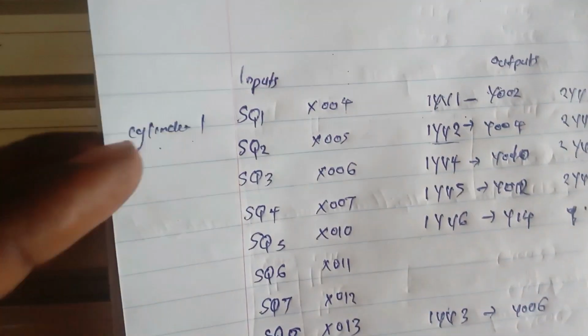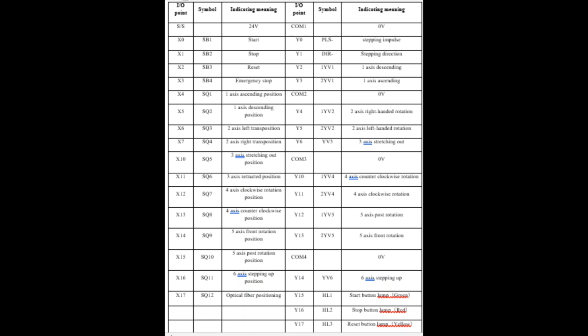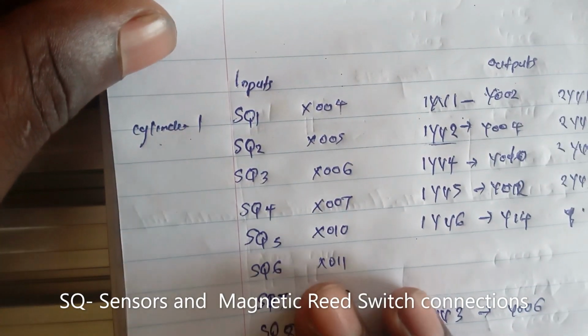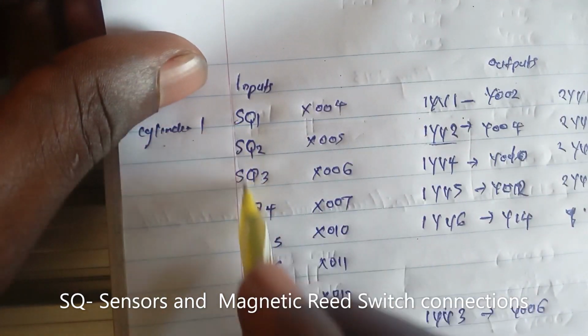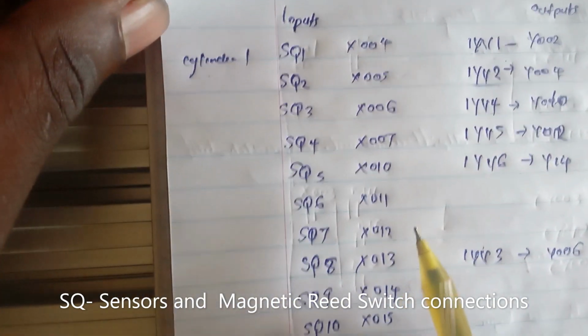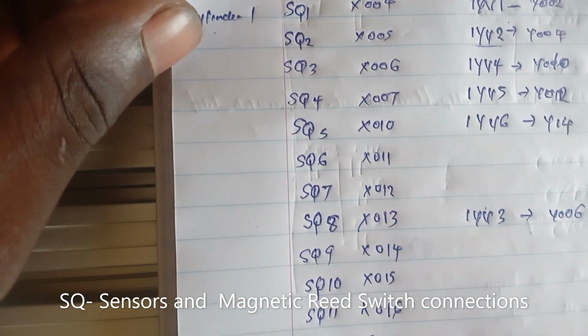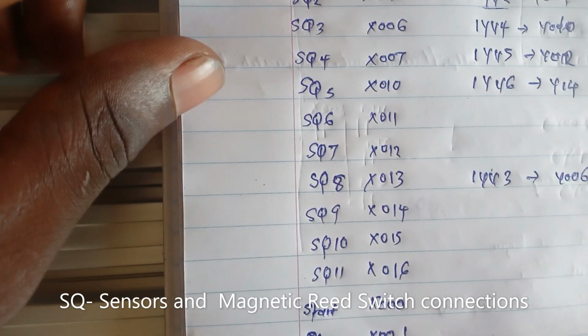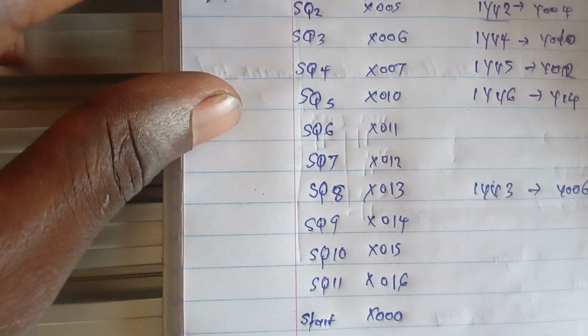To start off with this program, we need to create the I/O distribution table, or the I/O connection table. For the I/O table, we have SQ. The SQs are the magnetic reed switches and the sensors to which each cylinder of the robotic arm is connected. And we have the start button, which is connected to X0,